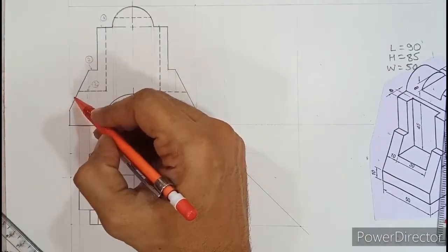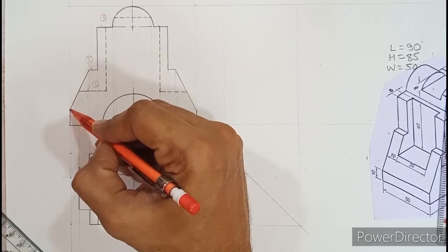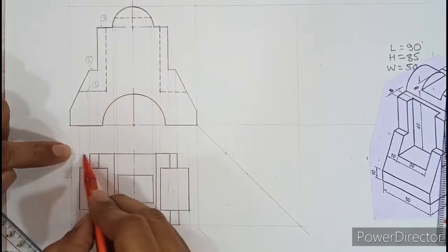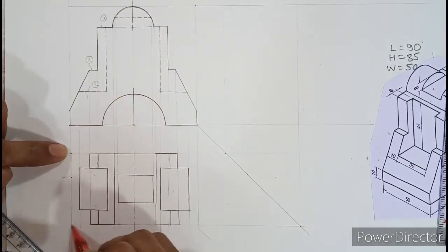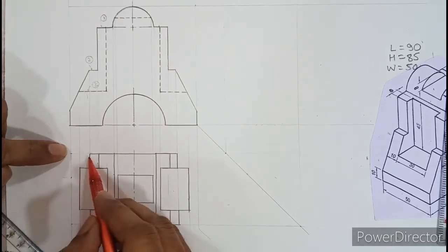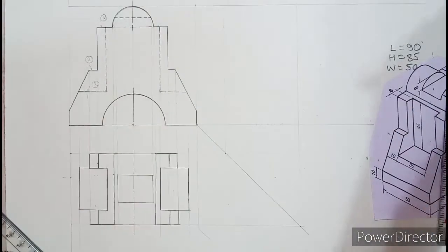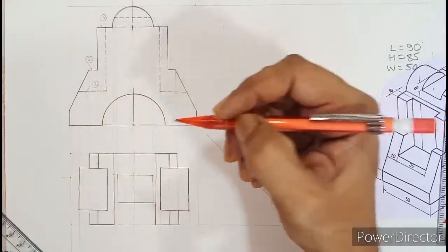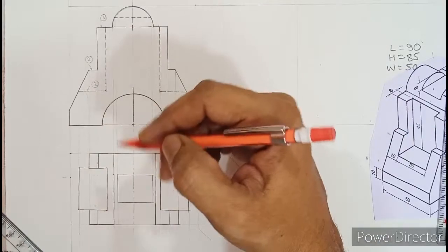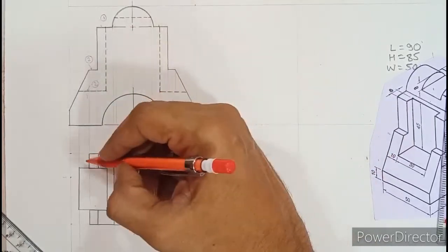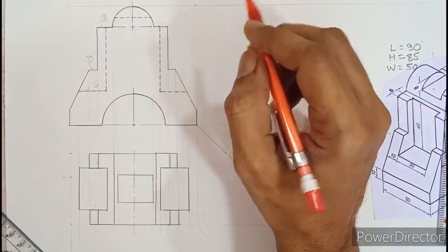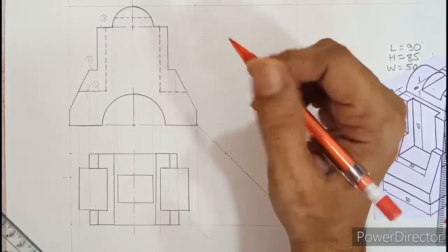If you look at this diagram, this is that inclined surface from here to here, and if I extend this down slowly, this missing part, first line, second and third, these three lines, if I connect this, I will get the inclined surface automatically in between. So what is the important conclusion we have learned from the last two questions is, in the top view, whenever you draw inclined surface, you always draw it at the end, because you're going to get it automatically. If you start with the inclined surface in the exam, you will end with inclined surface only. So always try to draw the inclined surface at the end after you complete all the flat surfaces, because flat surface is easy to visualize and draw. Inclined surface is difficult to visualize and draw.